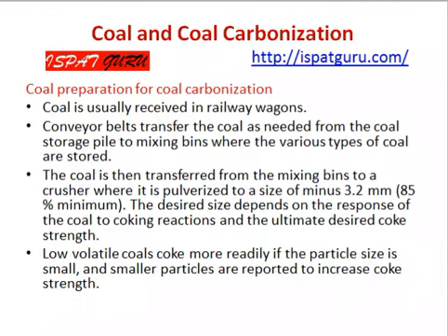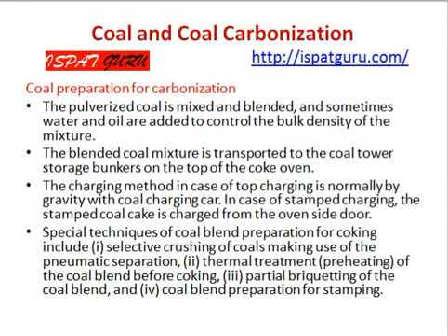coke strength. Low volatile coal cokes more readily if particle size is small, and smaller particles are reported to increase coke strength. The pulverized coal is mixed and blended, and sometimes water and oil are added to control the bulk density of the mixture. The blended coal mixture is transported to the coal tower storage bunker on the top of the oven.